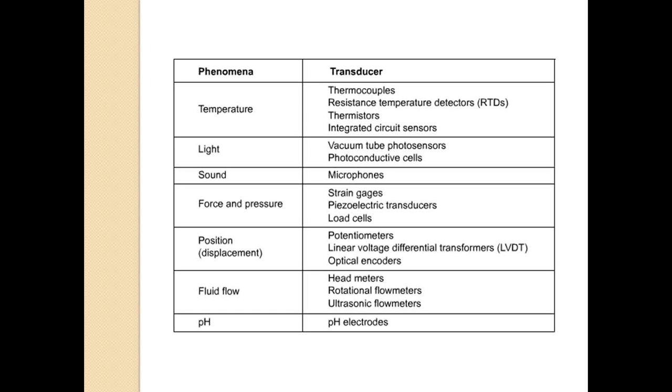Next you have plus 5 volt DC, plus 15 and minus 15. These are the main features of the DAC. Apart from this, it has a sampling rate of 200 kilosamples per second. So what do you mean by sampling? Sampling is the rate at which you want to acquire a signal, so that during your reconstruction phase you get a proper wave. I'll give you 2 demos on 2 sensors.